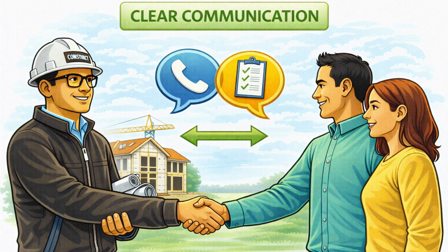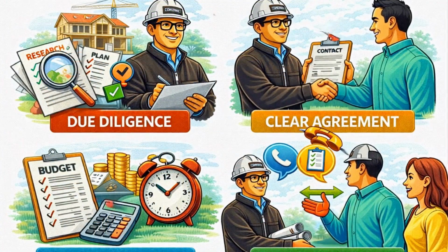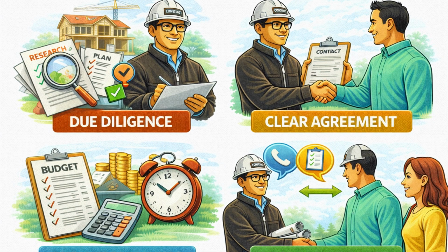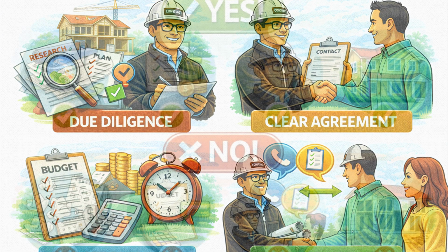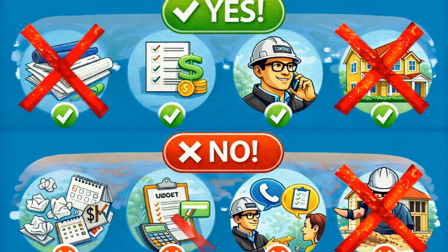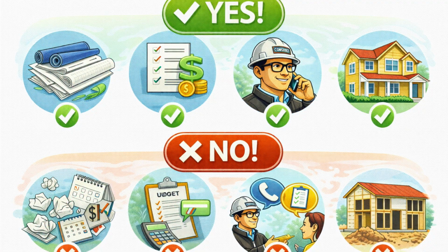Step 5. Control time. Use milestone tracking. Foundation complete, structure complete, roof watertight, MEP complete, plaster complete, finishes complete, handover. Even a simple milestone plan protects budget. For diaspora and tropical builds, this matters even more. Heavy rain punishes bad drainage. Humidity punishes poor waterproofing. Heat punishes cheap roofing. Distance punishes weak supervision. Your advantage is not hope, it's systems.